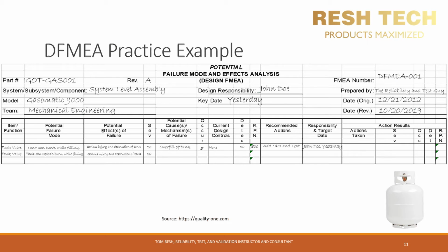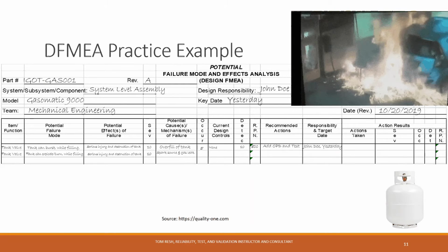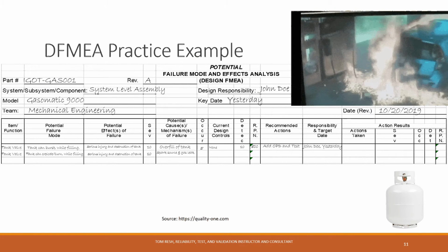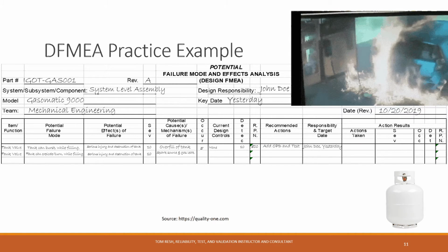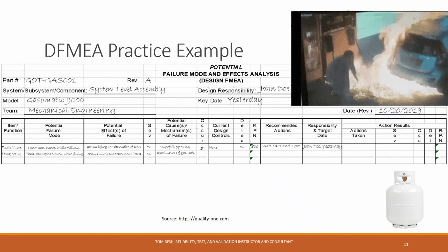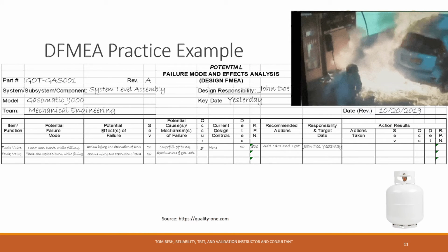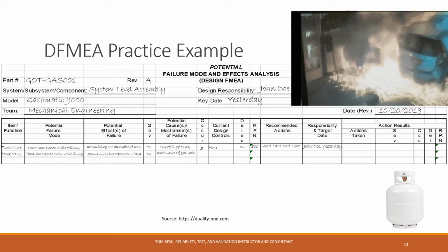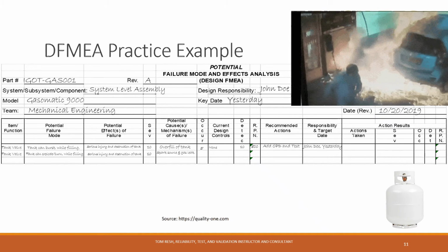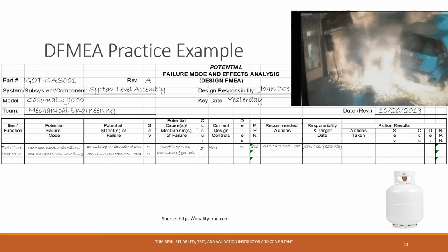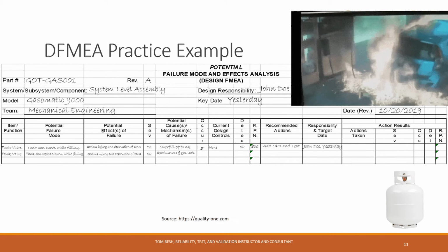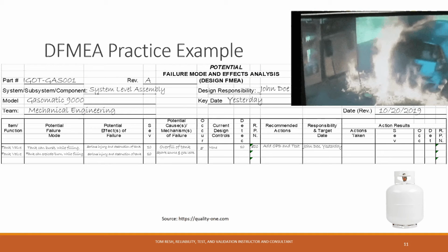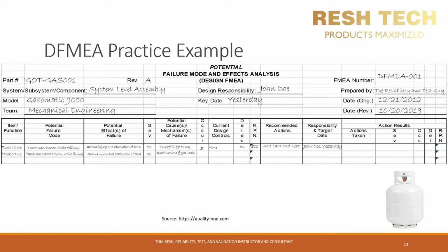Potential causes. Let's see, because people do stupid things, like smoke a cigarette while working with open combustibles. Of course, there needs to be a leak too, but with a combination of a careless person and a gas leak, it's a recipe for disaster. Again, I'm going to assume that 1 in 400 people are careless and also don't know how to properly tighten a fitting or use worn-out fittings and hoses that leak due to years of material aging and breakdown. So let's go ahead and put in a 5 for our number of occurrences.